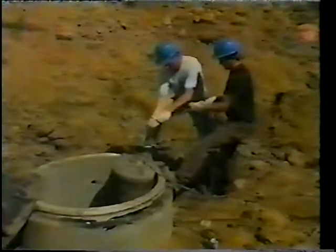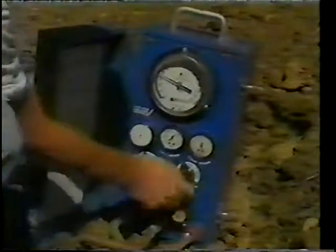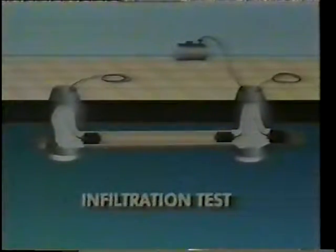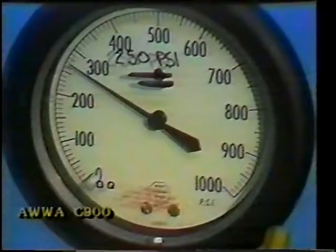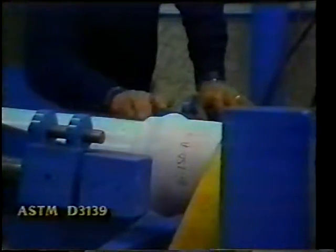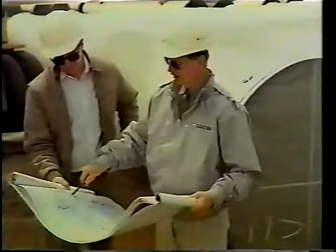Gravity systems are tested by using low-pressure air, low-pressure water, vacuum, or by measuring the flow of groundwater into the pipe. These and other tests assure the quality of the pipe soil system, which the designer designs and the contractor builds.